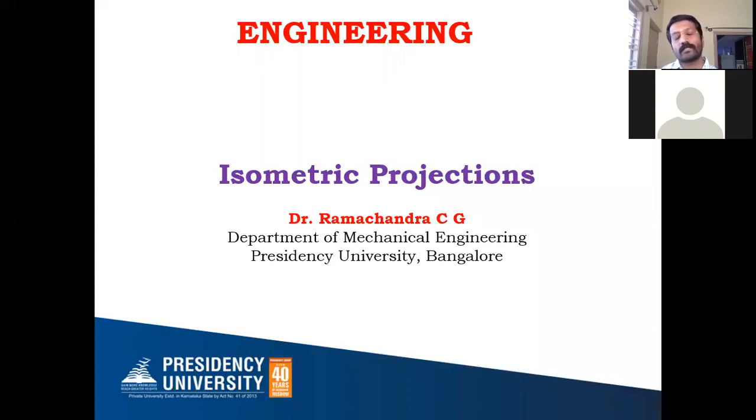In orthographic projection, what is the principle that we have used? It is ortho, it is 90-degree projection. All the projector lines from the corresponding points are taken towards the planes, exactly meeting at 90 degrees, or perpendicular. That's why it is called orthographic projection. We will go on to discuss isometric projection today, and all your orthographic projections are two-dimensional projections.